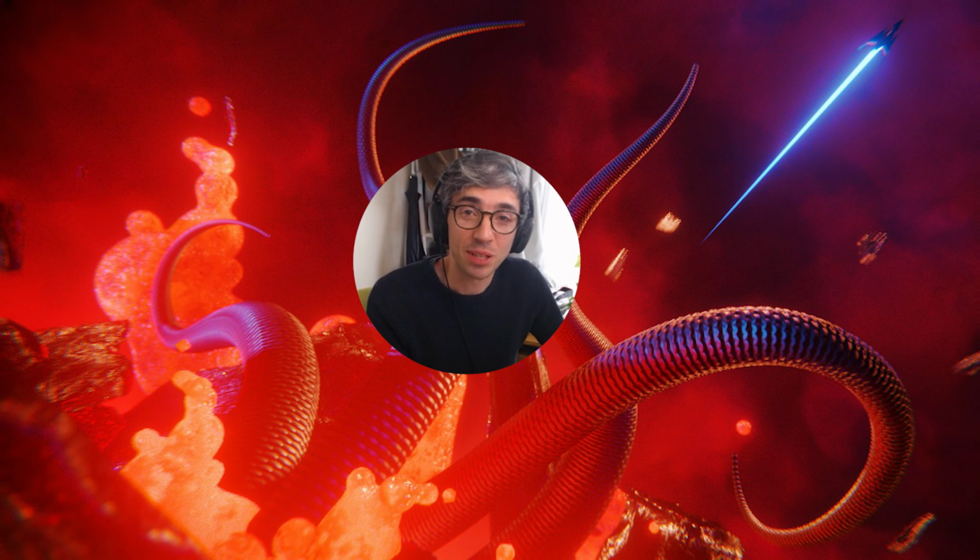First thing we're going to do is create a gradient texture. Okay, and let's plug this into the emission. Gradient texture gives us a gradient, so from left to right, you see black to white there. We're going to switch this to spherical. This will give us a circular shape. And I'm going to use the texture coordinate. We're going to use the UV as the vector.